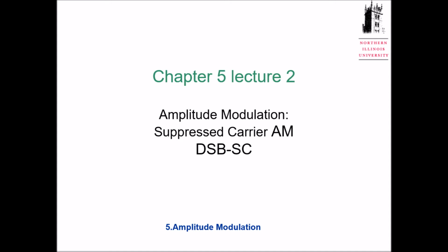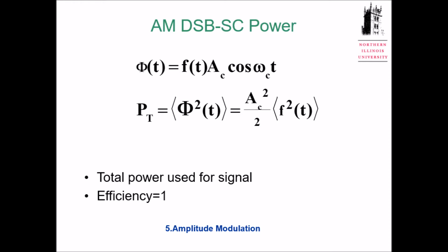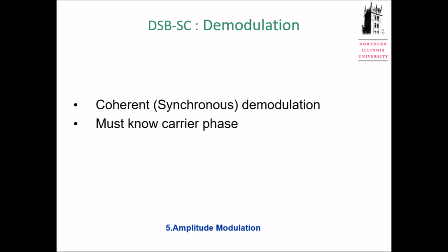Last time we talked about double sideband suppressed carrier, just no carrier, right? And in your time domain signal, there will be a phase reversal. And we mentioned my efficiency is 100%, right? All power is used to transmit the message. So we achieve the goal we wanted to beat, right? We increase our efficiency to 100%. However,